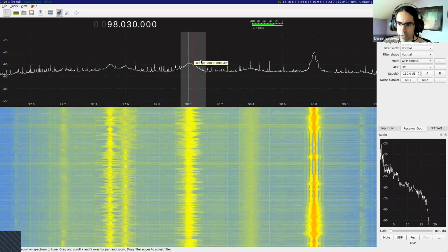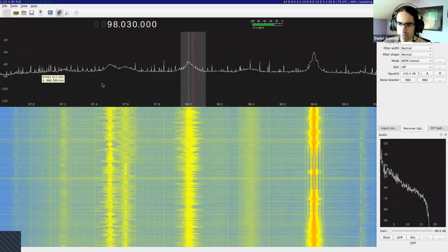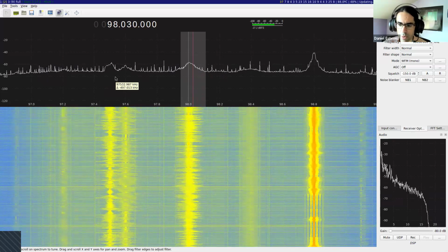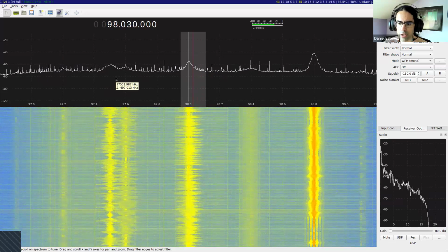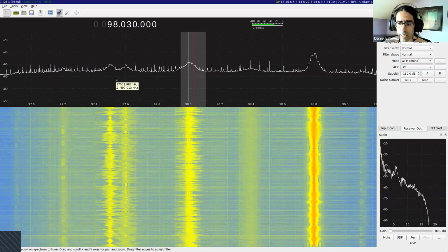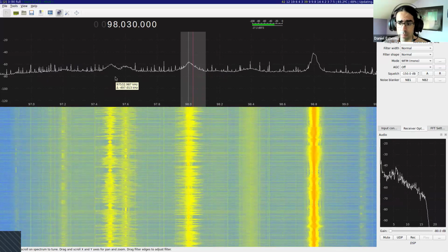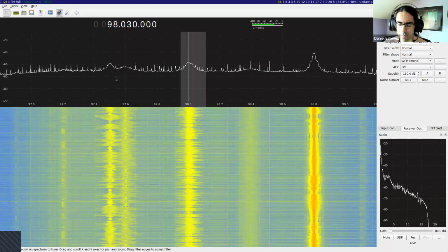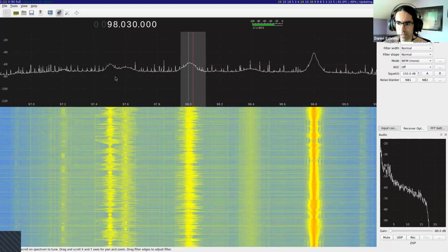But if this is at 0 hertz, then everything on the left needs to be at negative frequencies. So to sample both positive and negative frequencies, we need something which has basically two ADCs. It samples two different voltages, one which corresponds to the real part, one to the imaginary part.